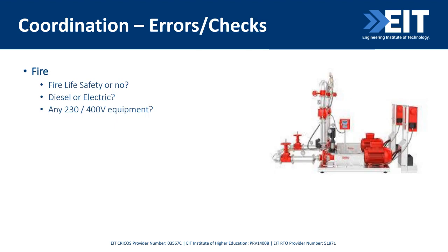So common checks. Is it a safety service or not? Because we would treat them differently. Not all pumps and not all equipment is a safety service. If they do have pumps, are they diesel or are they electric? Because there's a big difference for us in what the load is between those two. And in general, what equipment do they have and where is it? Often there's a lot of small equipment that can get missed that simply just needs a power point. So it's that final interface that we need to run through.